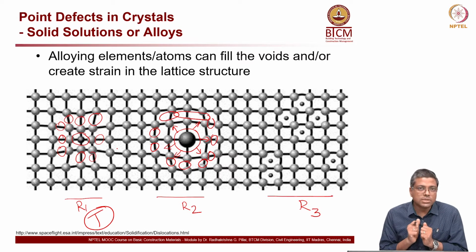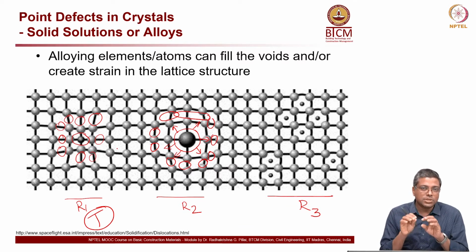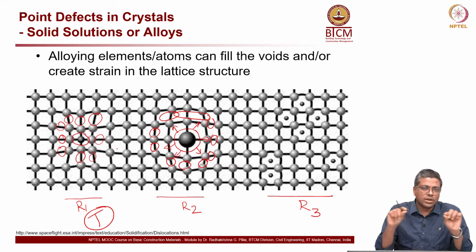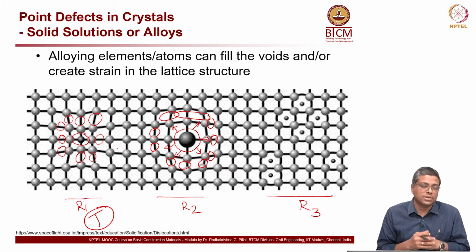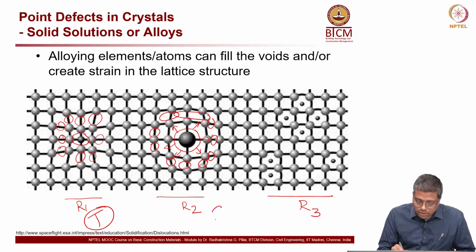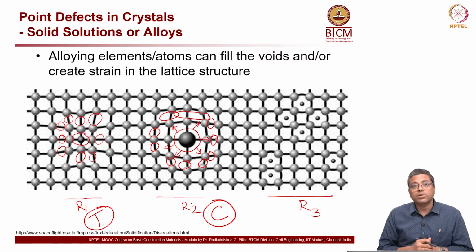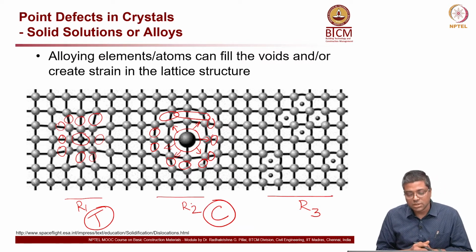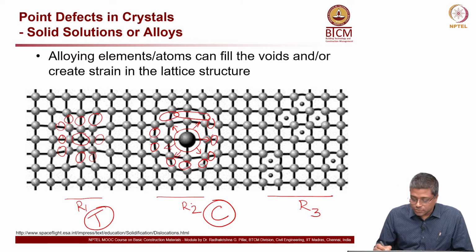This technology is used somewhere for pre-stressing. Even in toughened glass, they put some impurities so that some kind of compression is generated at the very near surface. So, you get pre-stressing effects. Okay. Anyway, this gives you a little bit of compressive stress in the region.